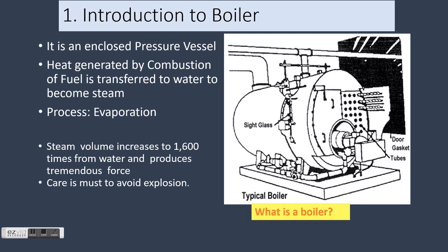Heat is transferred from one body to another by means of: 1. Radiation, which is the transfer of heat from a hot body to a cold body without a conveying medium. 2. Convection, the transfer of heat by a conveying medium, such as air or water. And 3. Conduction, transfer of heat by actual physical contact, molecule to molecule.